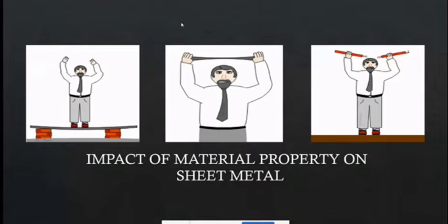The gauge of different sheet metal is usually discussed with respect to the average, but in reality the actual thickness can be anywhere within a specific range for the category. A variation of plus or minus 0.0006 in material thickness can represent as much as 4 degrees of angular variation. A very small variation in thickness can impact a bend angle by a few degrees.